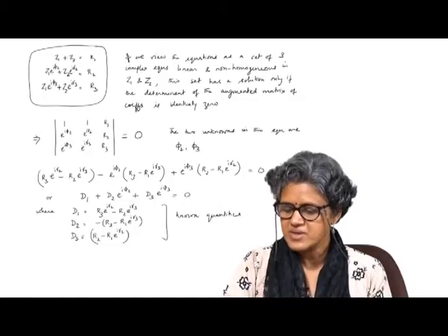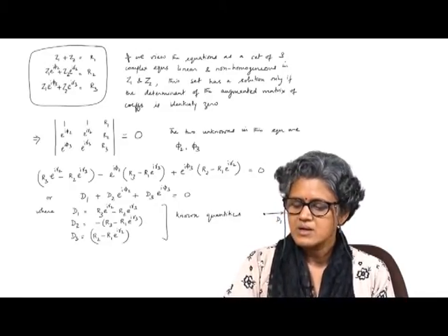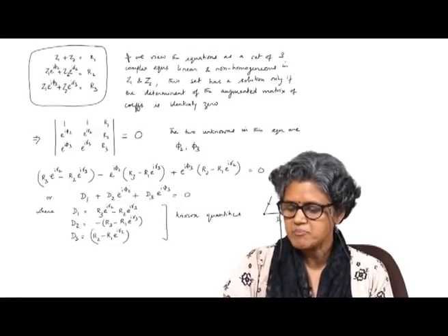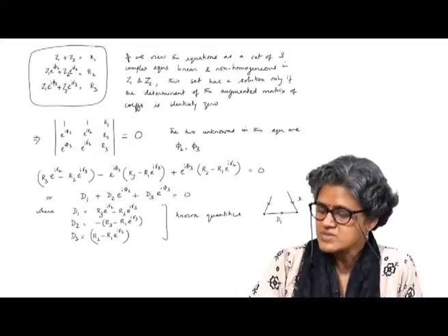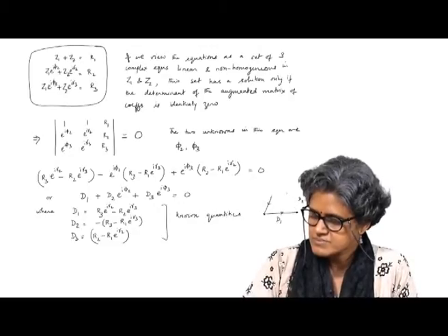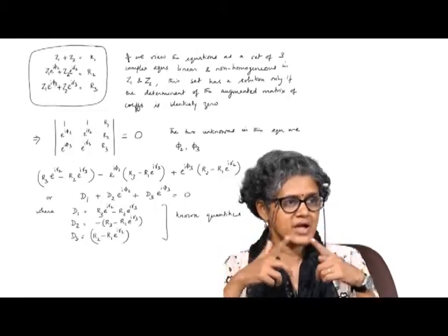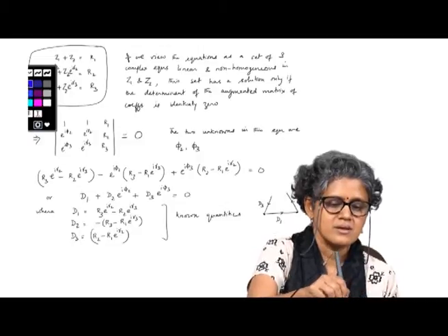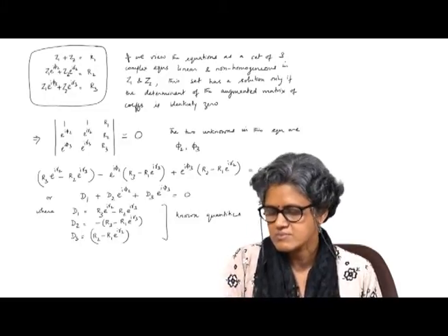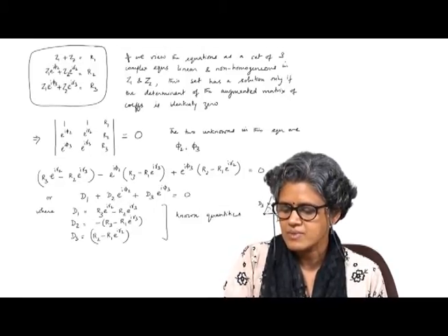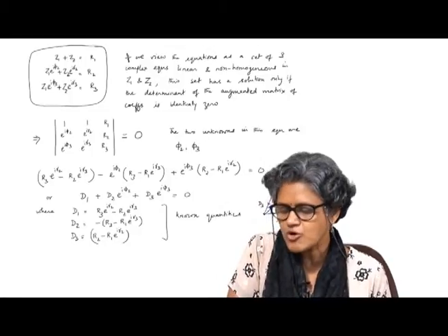So, one way to solve this is to consider the d1 vector and assume that d2 and d3 are pinned to this, on either ends of it. Say this is d2 and say this is d3. Then essentially what I am trying to find is through what angle should I rotate these two, say phi 2 and phi 3, so that they meet and form this closed loop.